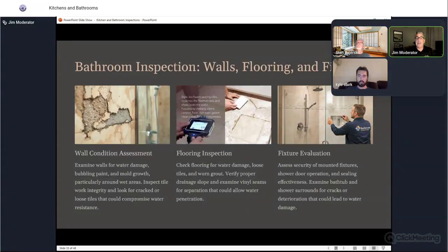What he's talking about is you plug your tester in, you hit the button and it doesn't work, but you hit the button on the GFI itself. So you're going into an older home that might have knob and tube wiring or ungrounded wiring. The way to fix that can be to put a GFCI breaker in there, and that is protecting the client, and that is acceptable. How I handle it, I don't fault it.